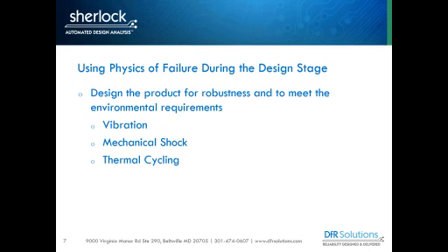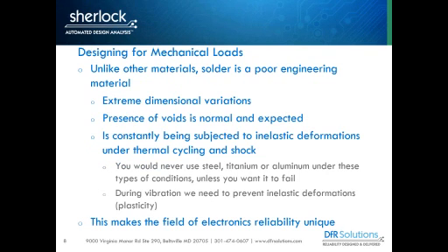Those are things that are a little bit more subtle, but when we see large recalls on electronic products, a lot of times it's a mechanical reason. And it could be very subtle mechanical issues. It could be underfill materials having low Tg. It could be bad plating on your circuit boards that's causing high stress concentrations in your plated through holes because of insufficient plating thicknesses. There's all sorts of different things that cause early failures.